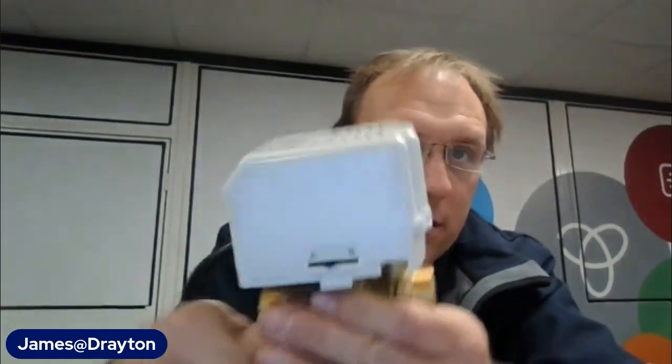But the great thing about this, and obviously you can see it from this, is that they're detachable by just pressing in the button. So when you're installing these, you pop your top off. You don't have to worry about the actuator being on, and then you can plumb away. Now with these, they are stamped underneath. You can see the ports. You've got A and B, and it's important that you get them the right way around. So you flow in on A and out of B.